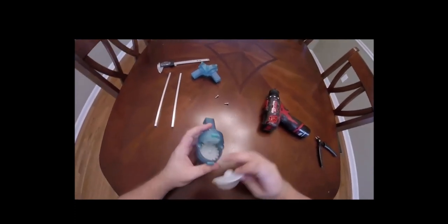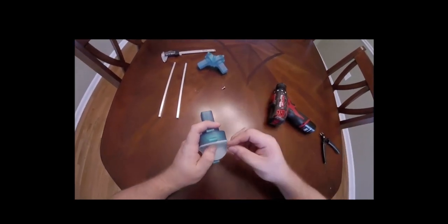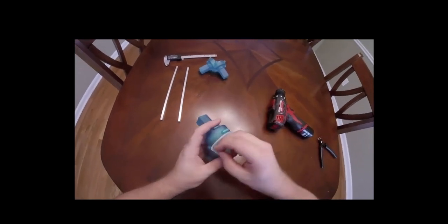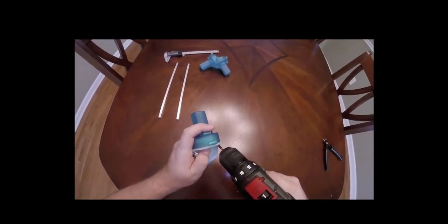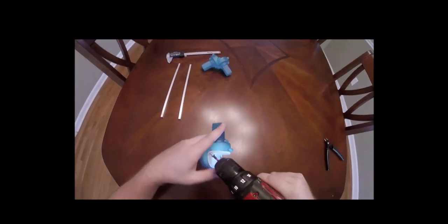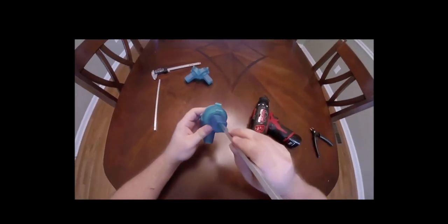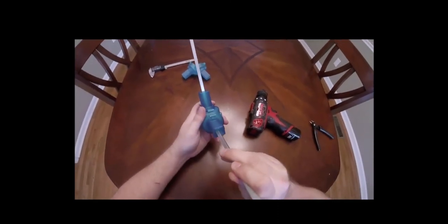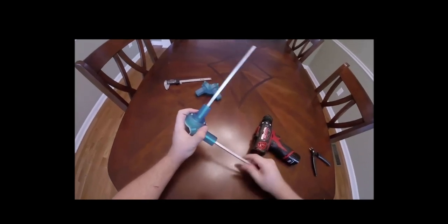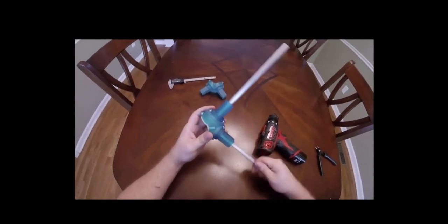Last thing is our retainer cover that also keeps the gears pushed back into place. These have slightly larger screw heads, so hopefully I don't need to change bits here, but let's give it a go. Yep, this bit's going to work. We've got a retainer plate on that's holding those gears back. You can see there are square drives down in here, which are where these two drive shafts go. So we slide a drive shaft into here, and another drive shaft into here. And now these turn each other, and this is what actuates the inside frame of the rotor casting unit that we're going to take a look at in the next slide.